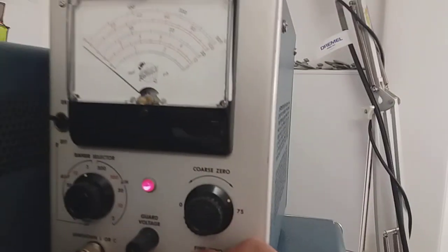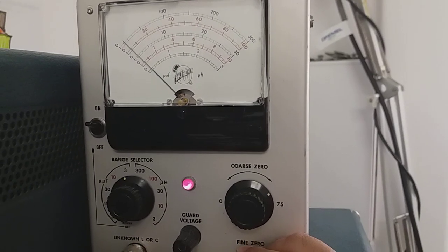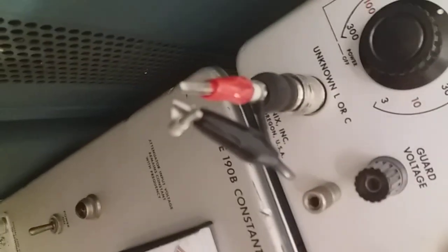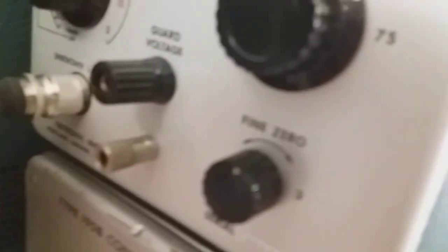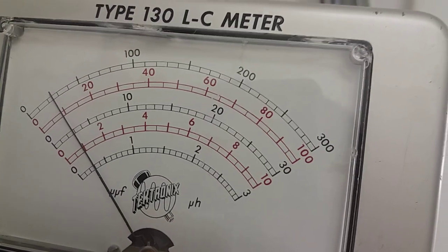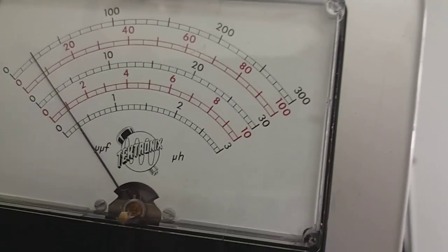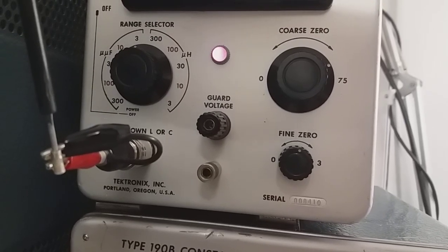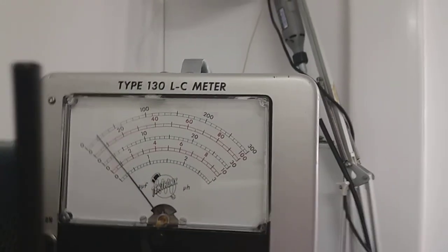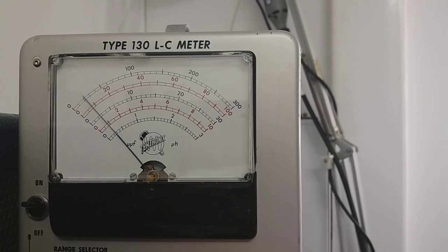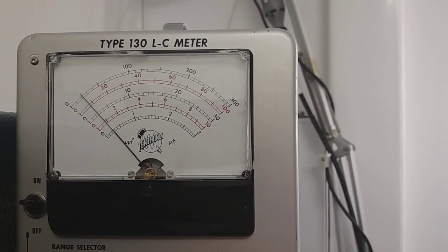But first I'm going to zero the meter, just like so. And then the probes are all ready, and then just clip both of them to the capacitor, the piston trimmer, and then I read that minimum capacitance is 0.3 picofarads. And as I go up and adjust the trimmer, now that's a little bit difficult to do with one hand, but as I go through, let me reposition the camera as I'm doing this, and that's actually a multi-turn trimmer, so I can very finely adjust. You see the capacitance starts to rise.